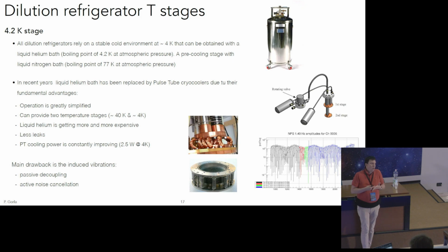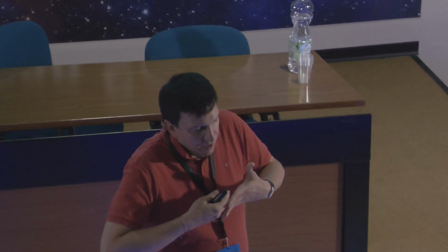So basically what you end up having is a pulsed expansion into this tube, which is then pumped away by the compressor and re-injected. And this kind of expansion through a specific orifice, which allows a dilatation after the orifice in this tube, is the part of the thermal cycle that guarantees the temperature lowering.